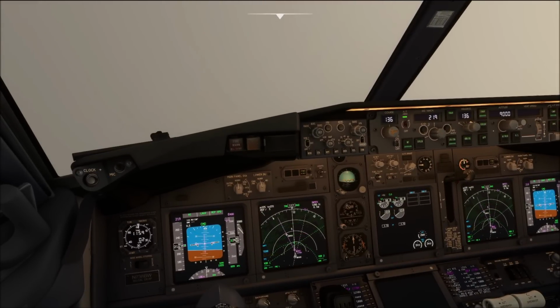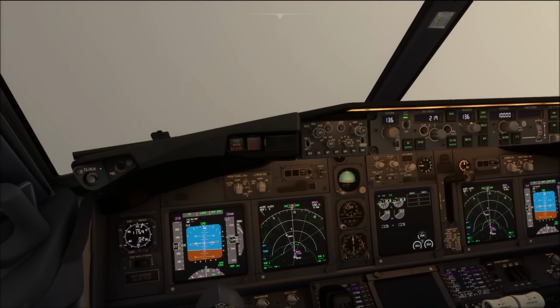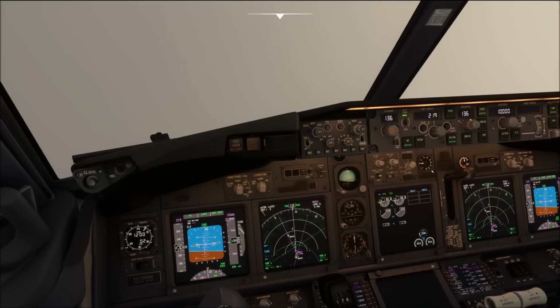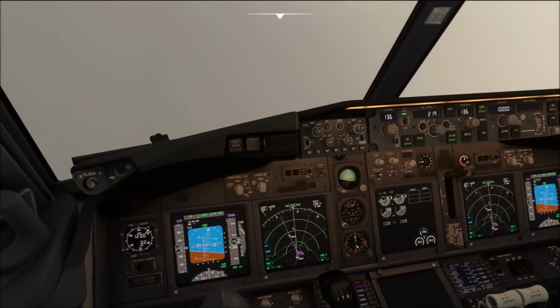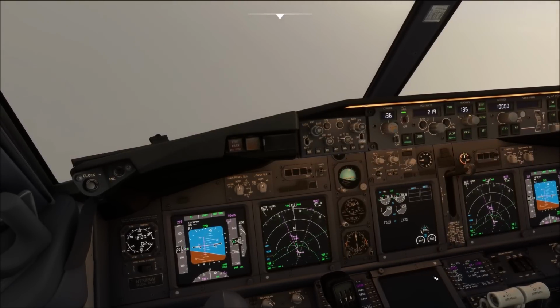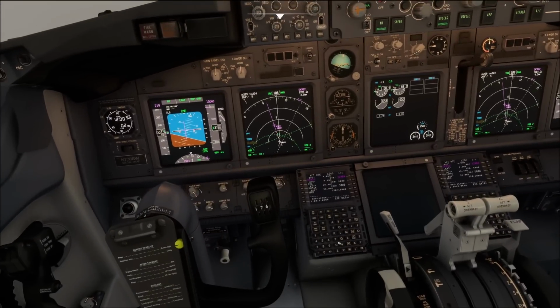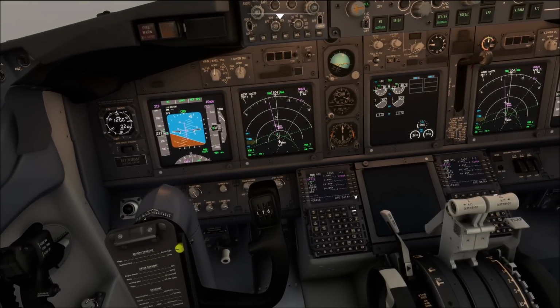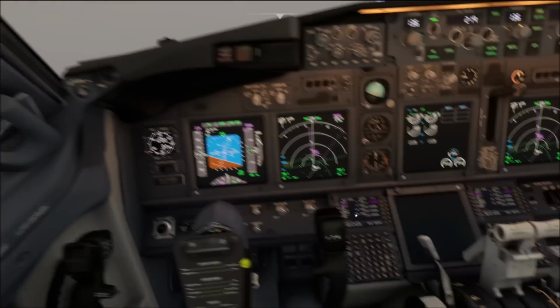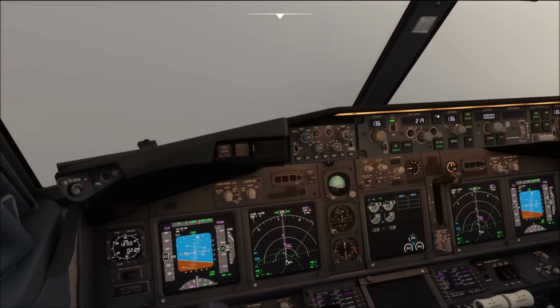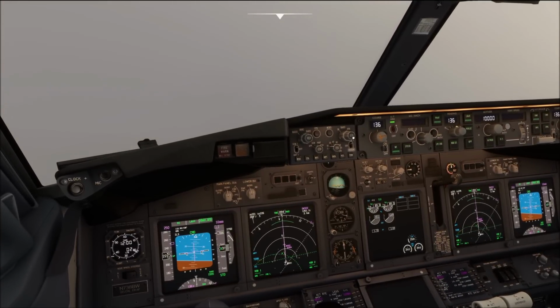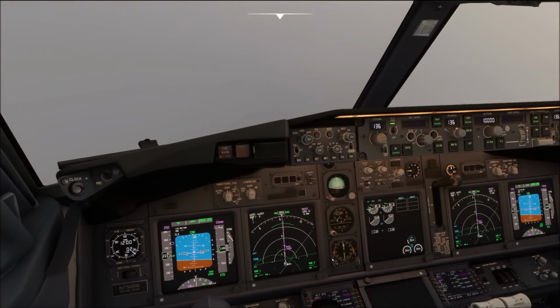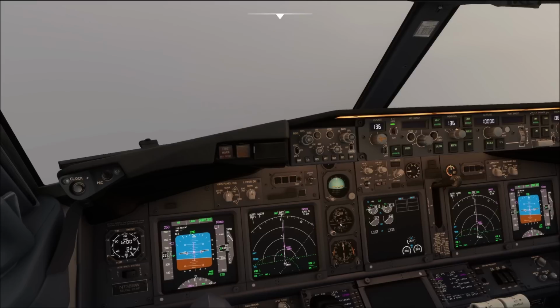Okay, let's assume ATC has just cleared us up to flight level 100. We have ensured that we are going to clear any of those altitude restrictions, so let's go ahead and delete that initial climb restriction. And we have flaps up, no lights. VNAV, set standard, passing 40, climbing 100, after takeoff checklist.